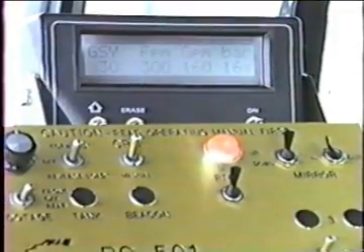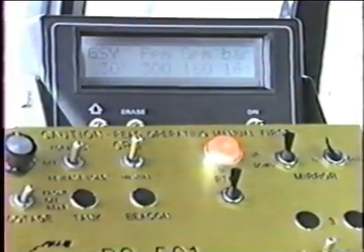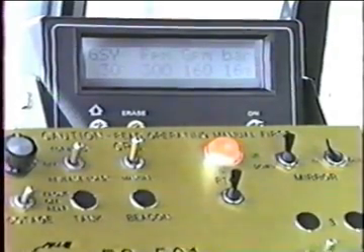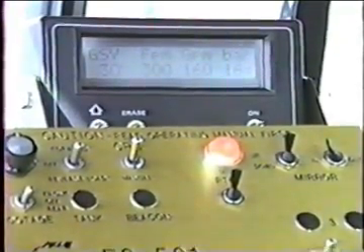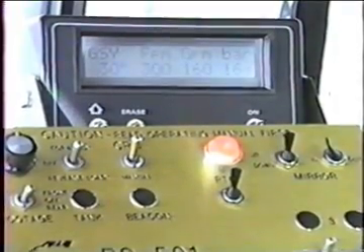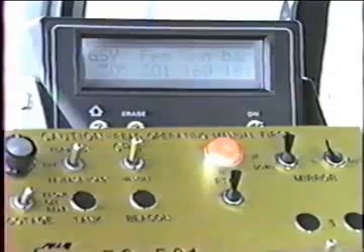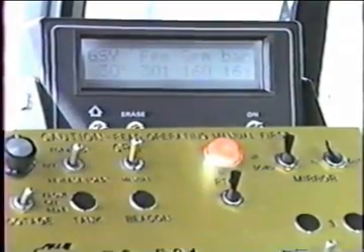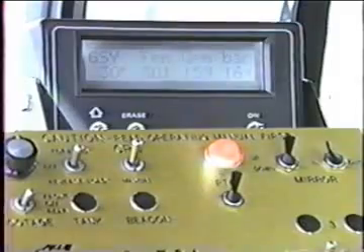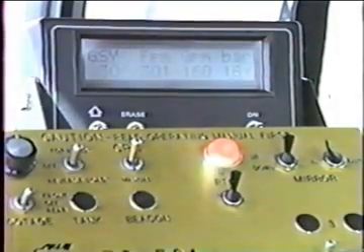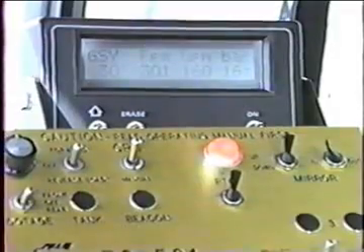We have 16 feet of spray bar, and you can see that we're clicking back and forth from 159 to 160 gallons a minute. That's 10 gallons per minute per foot of bar, or 10 times 16. It's a quick, simple test to see if the computer is driving the pump at the right speed. That is, set 3/10 of a gallon into the computer, hold the truck at 300 feet a minute, and see that you have 10 times the bar width in the GPM.